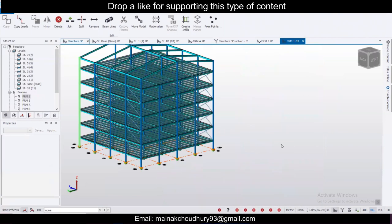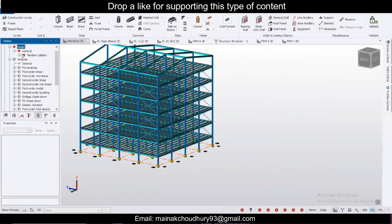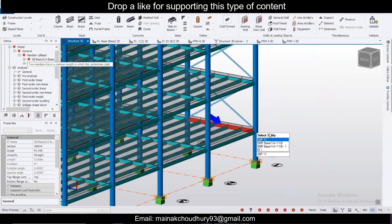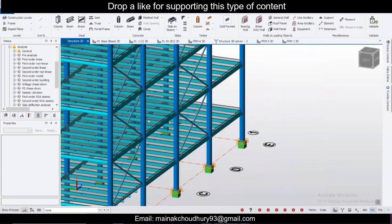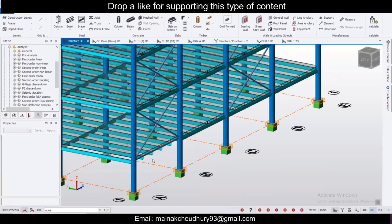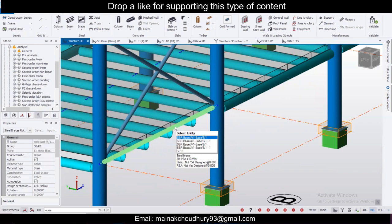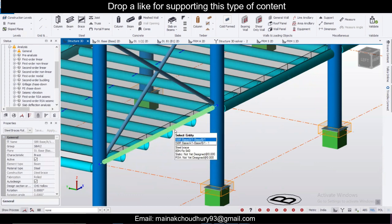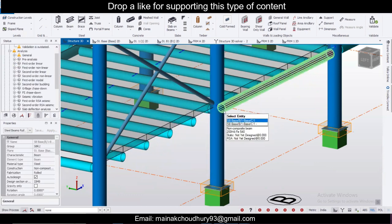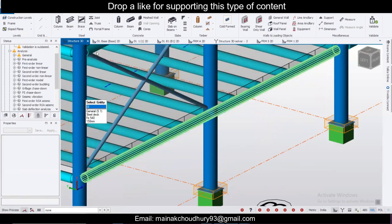Click on escape, go to structure 3D. Simple to validate because I think that I have made a member collision. Yeah, I know. So, I think I need to delete the member here once. No, yeah, this is the bracing. I need to delete the bracing actually. I provided two bracings here, but without deleting. Select this, delete, select this, delete. Then I'll just select this and extend this to here. Now it should be okay.